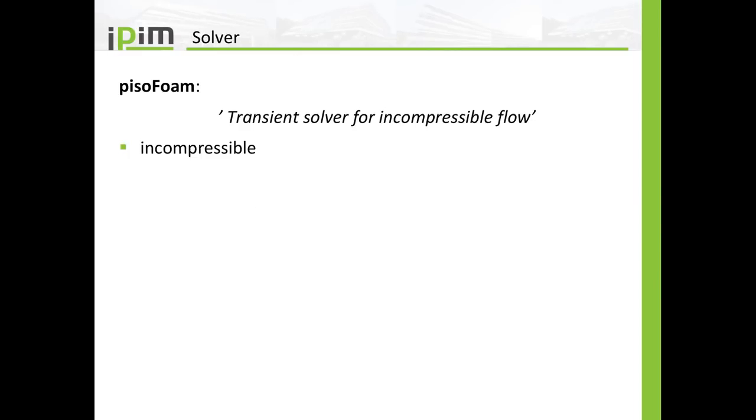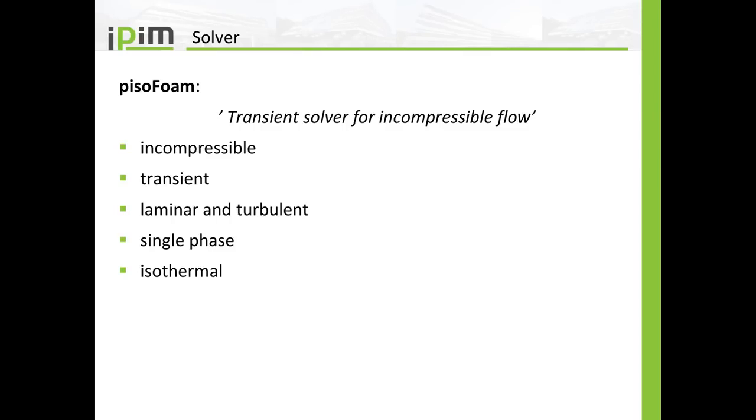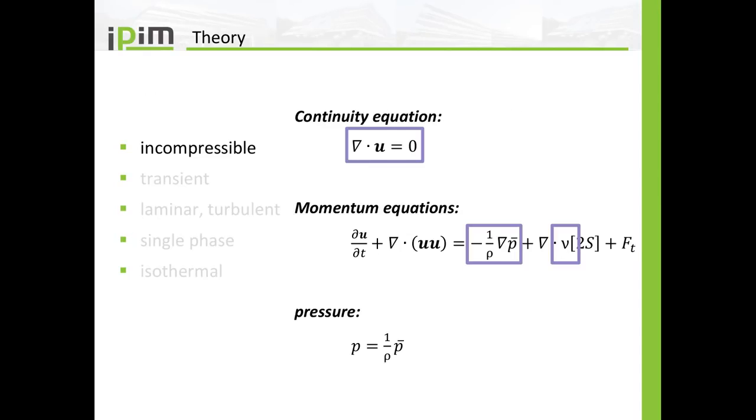For that we will use the pisoFoam solver, which is a transient solver for incompressible flow. At least this is the official description. So it is incompressible, it is transient, it works for laminar and turbulent flows, it is a single phase solver, and it is an isothermal solver.